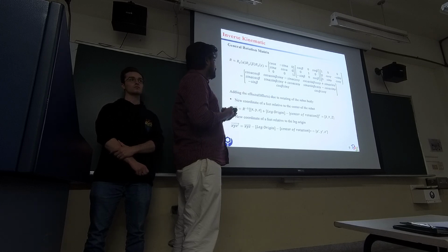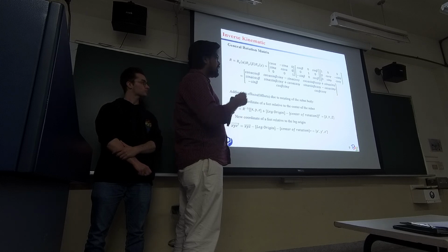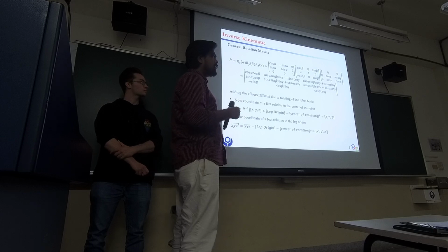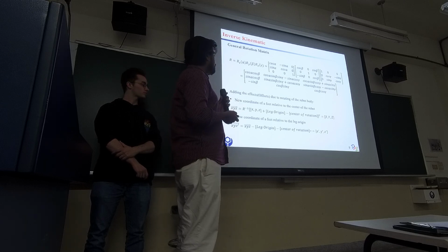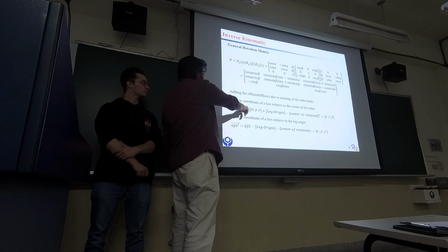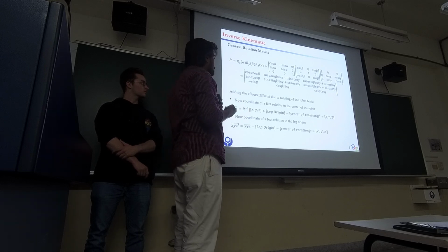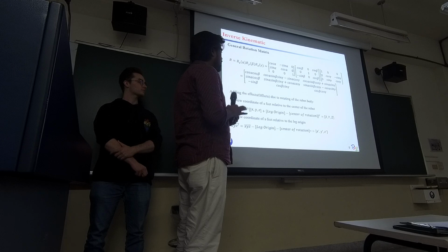To get the new coordinate of the foot related to the center of the body, we first calculate the coordinate of the leg origin and then the foot point. The new coordinate of the foot related to the center of the robot involves the rotation matrix, the x, y, z coordinate, and the leg origin and center of rotation transpose. Then we will get an x, y, z matrix.